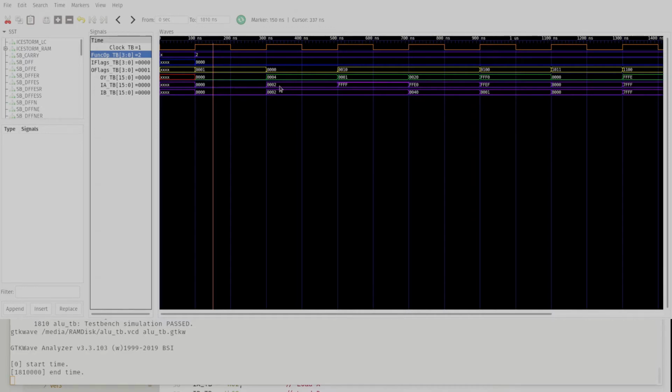Now here we are on the 2 plus 2. We expect 4, but the 0 flag is not set, which is what we expect because 4 is not equal to 0. On the next one, we're going to add the previous B value, which is a 2, to F. And we do expect a 1 because it rolls over to a 1. However, it also caused a carry, so a carry rolled over, and that's what we expect. In the next one, we purposefully set up an FFE0 and a 40, and we add those together, a carry is generated, which is what we expect.